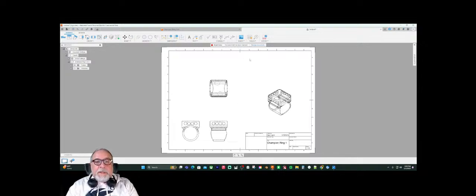So with that, then from here, you would go in and actually do all your dimensions. So you can click on the dimension component, click on a radius. It'll tell you what that radius is. You can set that. You can pick a dimension, like how wide this is. Pull this up. Do that for each one of these little holes. And then we'll set that. So anyway, that kind of gives you the idea as you go through each one of these.